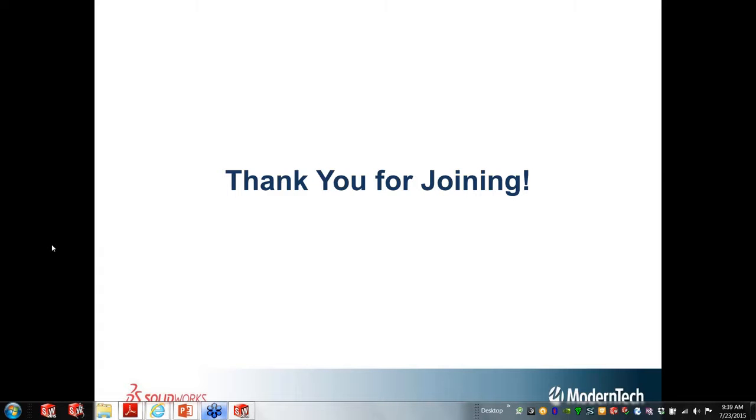The first question is, what's the time duration to obtain solutions through simulations? It depends on your mesh density, your processing power, and possibly how cool you're keeping your own computer. Just kidding, but that's actually very true. The simulations I ran with the rotating region took about 10 minutes. The lower the mesh density, the quicker they run. I've run some simulations in less than a minute. They're simpler, but the more complicated your system and the higher your mesh density, the longer it takes, anywhere from a few minutes to much longer. It just depends on how refined your mesh is.